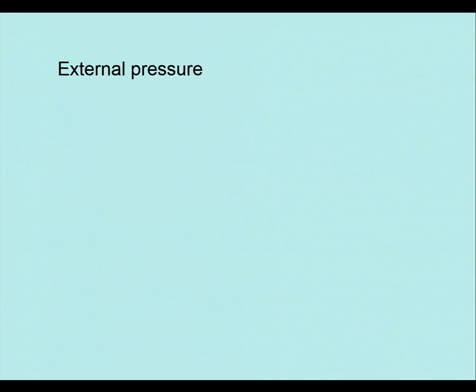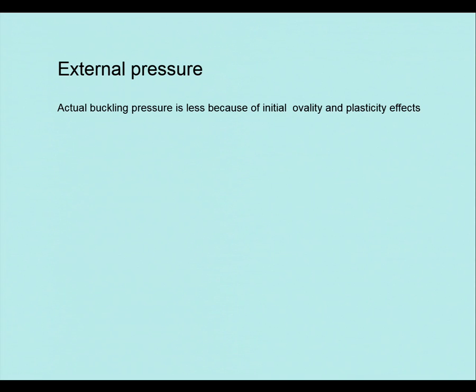So the actual buckling pressure is less because of initial ovality. We manufacture it oval, and we put it on the seabed and we bend it.